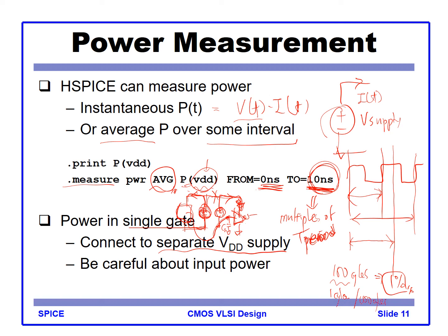So you should not increase the size too much for a typical gate. When you size the devices, we just size them based on the fan out, right? If you keep a certain fan out, then the delay over each stage will be similar, so in that case the overall performance will be optimized. Okay.